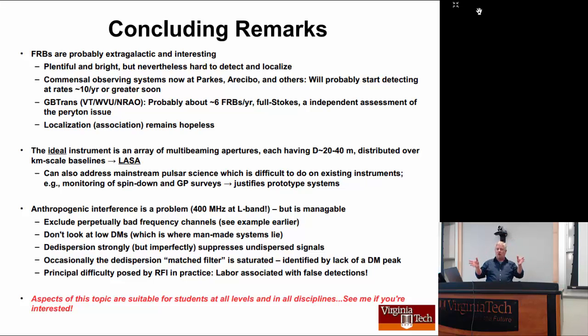is the fact that all modern radio astronomy science is not in narrow bands, but huge bands. Everything I do is over hundreds of megahertz of bandwidth, right? We get away with it here only because comm people haven't figured out how to stuff that spectrum with signals yet. So the real contention is not about levels. It's about how to do some kind of time frequency multiplexing so that when engineers figure out how to stuff the spectrum, we can still use those kinds of bandwidths. You think it's bad here.